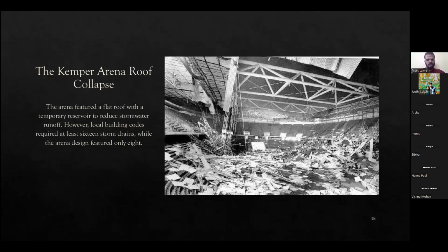So even in our structural firm, we get drawings to review from mechanical, electrical, and plumbing teams. They give us their drawings, and I really did not understand the purpose of doing that. I always felt this is not my job. Why should I review plumbing drawings? But then I could see my boss finding major structural flaws from the plumbing drawing. He would come to us and show us that you see, these two pipes are going through one of our critical beams. If they drill through our beams, it makes our beams unstable. We have to ask them to reroute their plumbing.